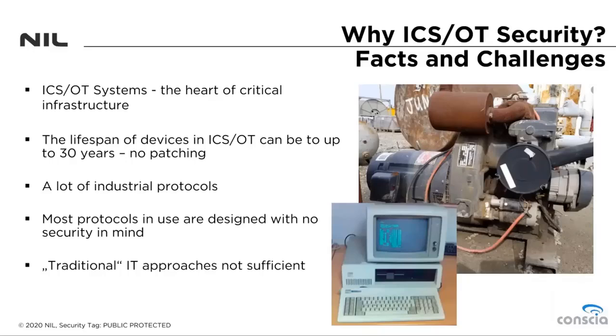But besides legacy devices, also protocols are an issue. Almost every vendor has its own protocol, and the protocols were not designed with security in mind. If we see encrypted traffic in an OT network, then most probably we have malware in our systems. Encrypting or not encrypting is actually today a hot topic in the OT world.